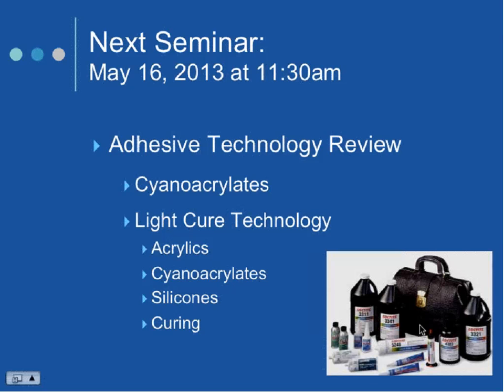There is, and if you go into your bonding plastics guide, we've updated the shelf life policy on page 89. It is better, I would say, to look at the TDS of the product because that gets very specific. It tells you exactly what you need. This one's very generic. For cyanoacrylates, it's this. For acrylics, it's this. But at least it gives you that. And on every package, we give you a use-by date.